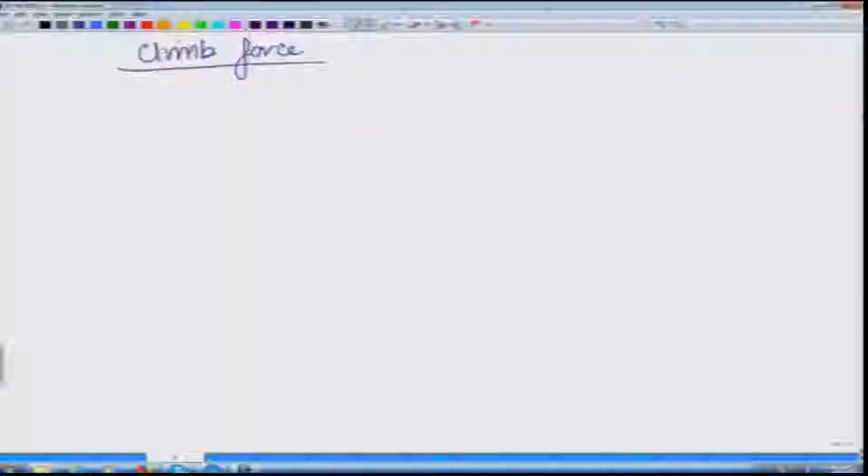Let us say you have a dislocation somewhere like this. So there are planes over here, there is the dislocation line, and then again there are planes like this. Now this dislocation, which is a line perpendicular to the screen, can either move up. If it moves up, climbs up, it will look something like this.